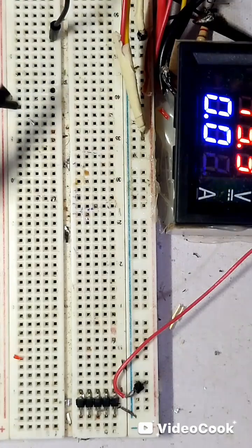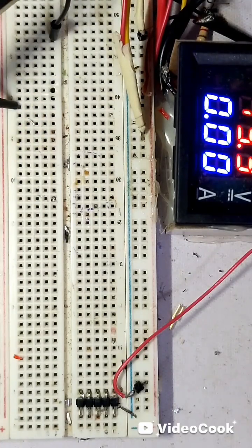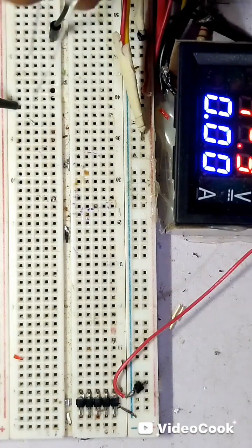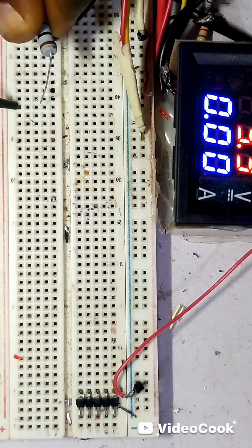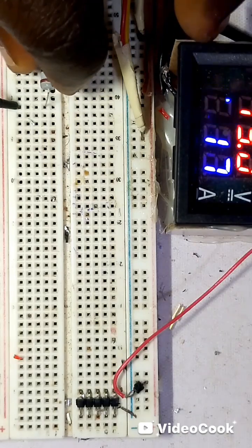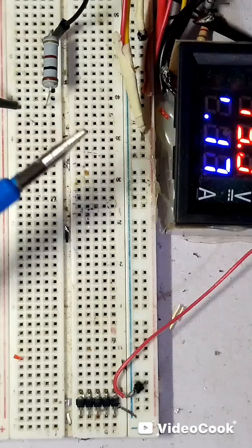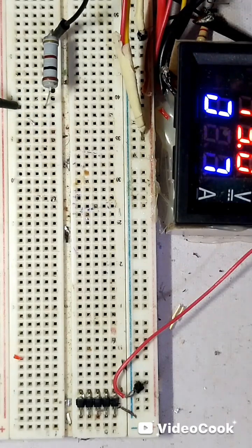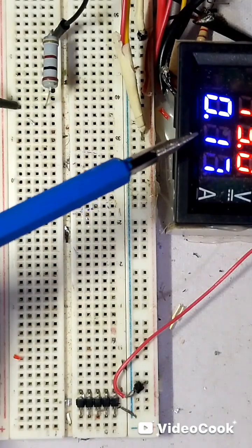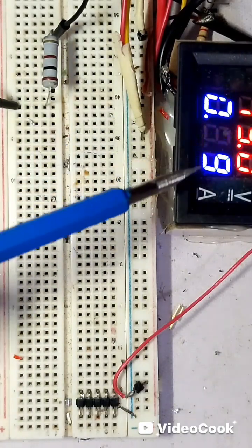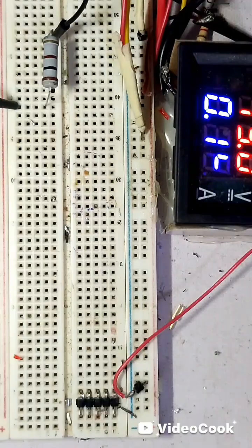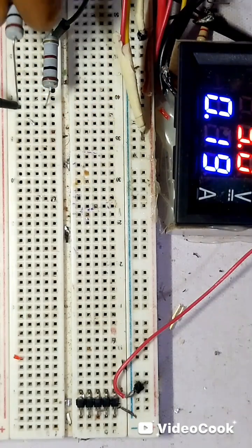This is our power source, positive and negative. First, I'm going to use the first resistor and load it across the power source. This is in parallel to the power source. One terminal is connected to the positive and the other terminal is connected to the negative. Now, if you look at the current meter, it's reading 0.17 amp. That's the current reading. Now, what happens if I parallel another resistor to it?